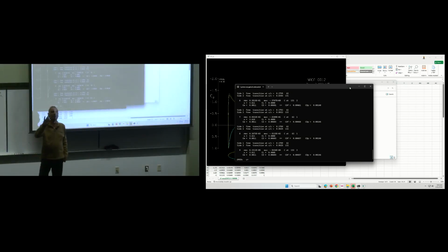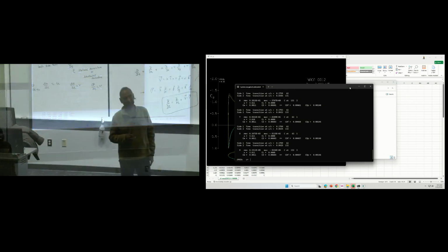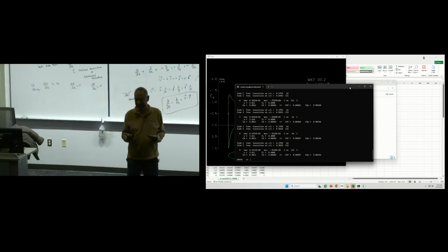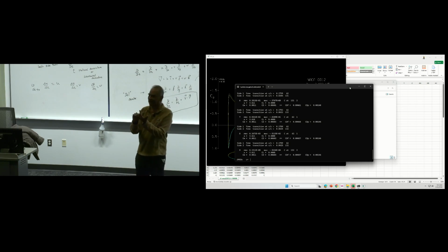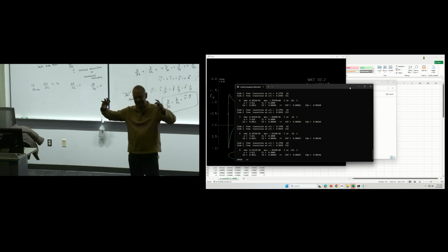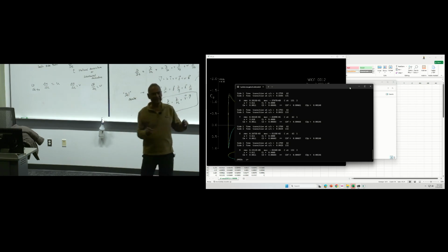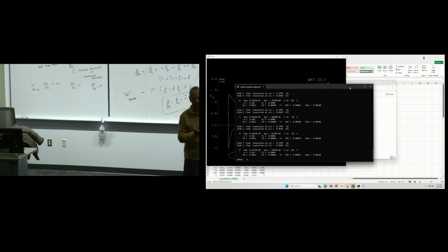So if you have a problem converging, of course the airfoil may be stalling or there may be some physical reason why it's not converging. This is not a cure-all, but we know NACA 0012 at 4 degrees should not be separating, should not be anything weird going on. So the most likely reason is because we don't have a sufficiently refined number of points. So you could use commands like PANE to cluster it near the leading edge, trailing edge. You could also try PCOP and see what happens.